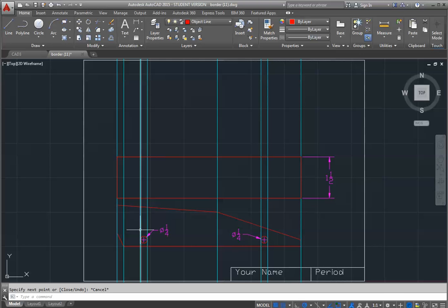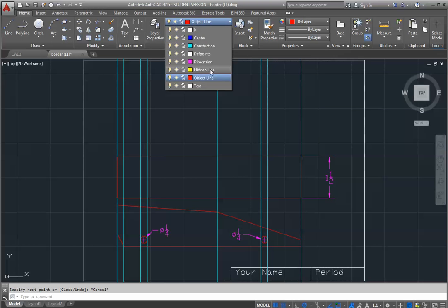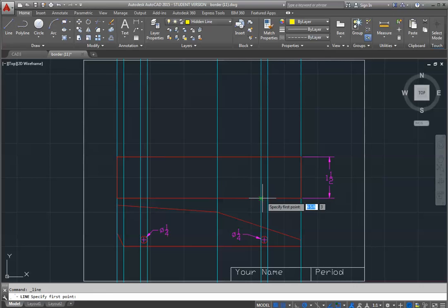So now I have to determine what lines can I see, what lines can't I see. The lines that I can't see are this hole that goes through the front view. So that one's going to be a hidden line. What other hidden lines do you see? Are there any others? Am I done? Zach? There's still one more hidden line on the other wheel. On the other wheel? Right here? Yeah. Am I done? No, we still got to do the other side. Okay, I got to do both sides. This represents the wall or the side of the holes as they go completely through the block.